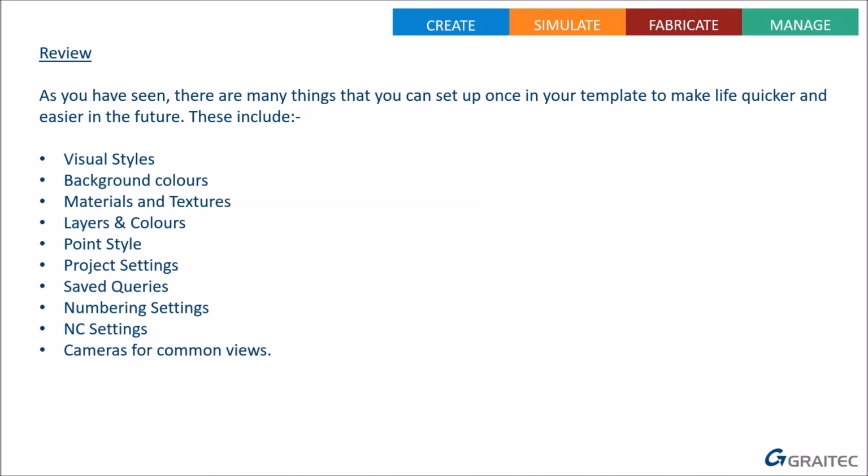You should also think about some saved queries. Definitely you should have one for no model roles, or model role equals none. But we suggested some others like lotting and phasing, material, and so on that you can set up as saved queries to help you manage your project. They can all be set even though the file's empty, doesn't hurt, and they're just sat there in Project Explorer waiting for you in future.